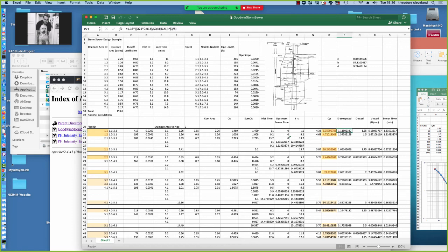We apply the diameter equation to compute a required diameter, and that comes out to be 1.11 feet. We would probably select something a little bit more commercially available. So here we're doing 1.25 feet, a 1¼ foot pipe, which would be 15 inches inside diameter. I'm really not sure how available that is, but I know that 1.11 feet is not at all available.